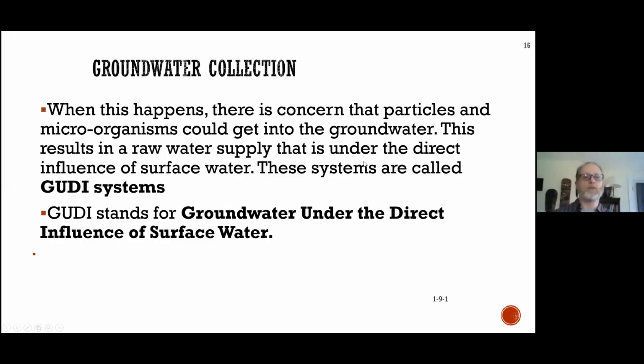But basically the same principle is we're going to drill into the aquifer. We're going to set a casing, secure it, support the material around the well casing, and then protect that well from contamination. But sometimes we have to do it more than once.